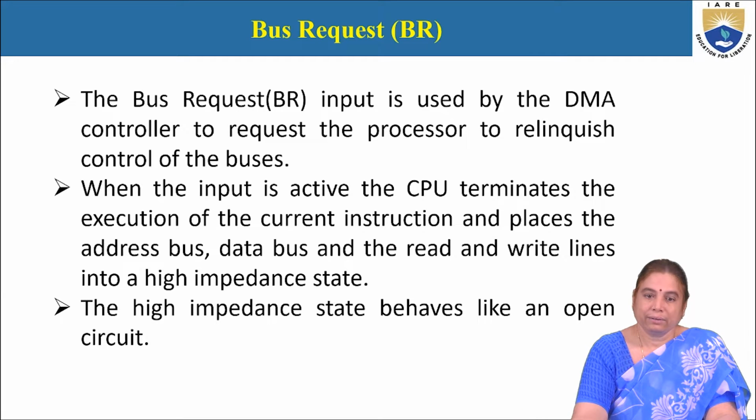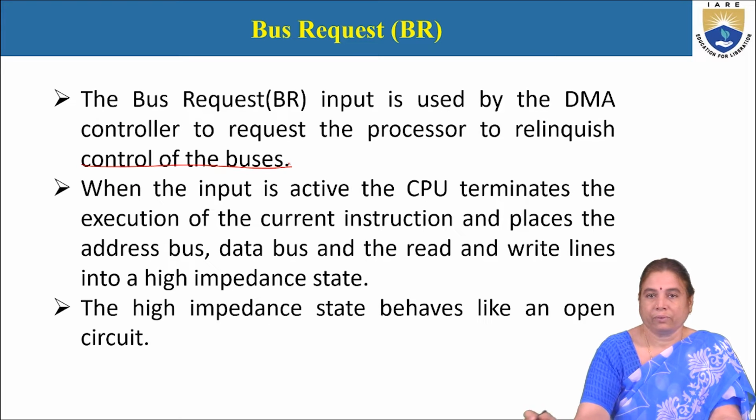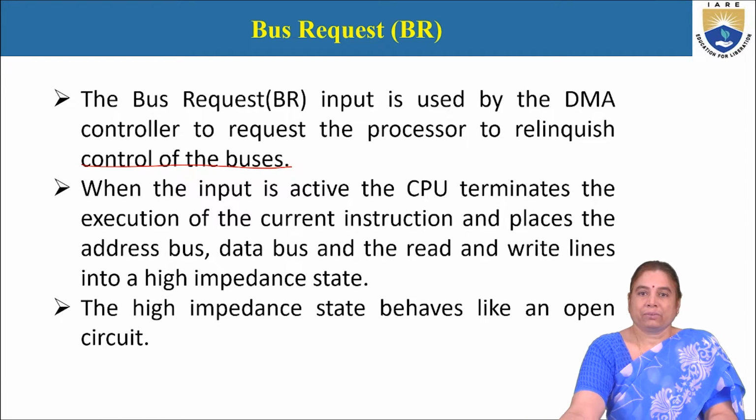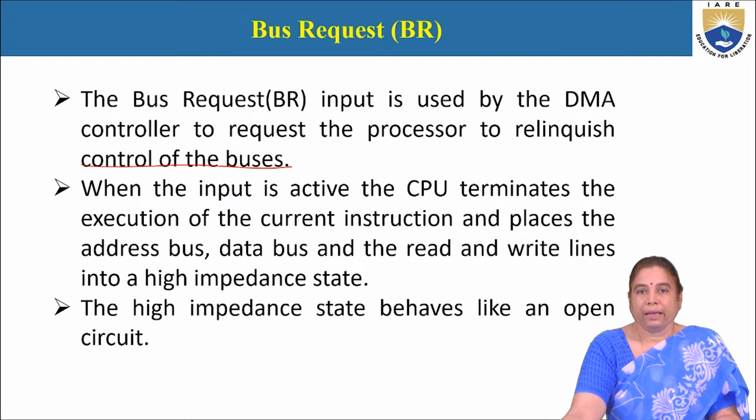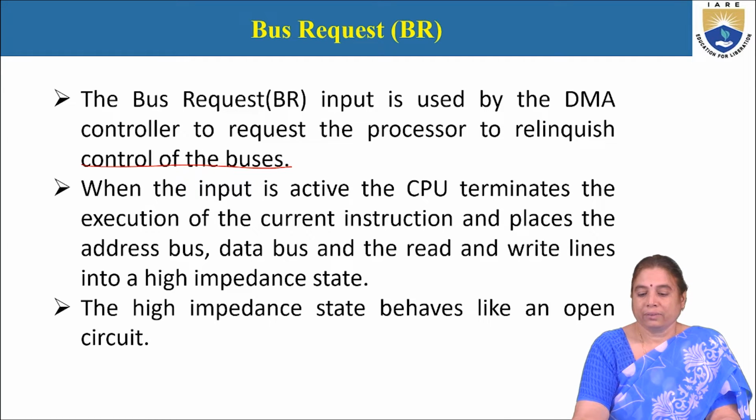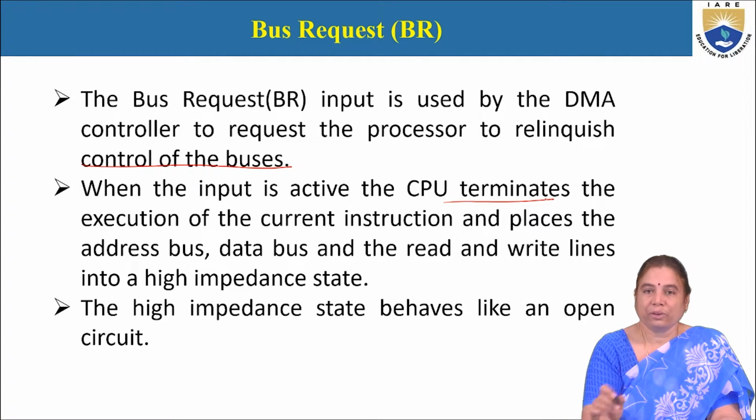So what is bus request? The bus request input is used by the DMA controller to request the processor to relinquish control of the buses. Whenever the bus request is received by the CPU, it has to put the circuit in the high impedance state, and it disconnects from the external circuit. When the input is active, the CPU terminates the execution of the current instruction and places the address bus, data bus and read-write lines in the high impedance state.